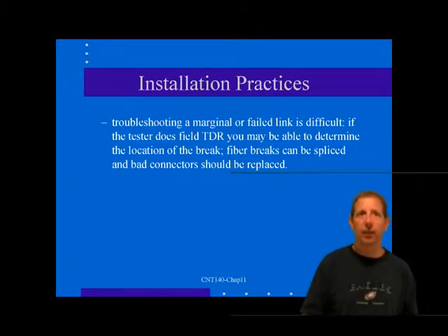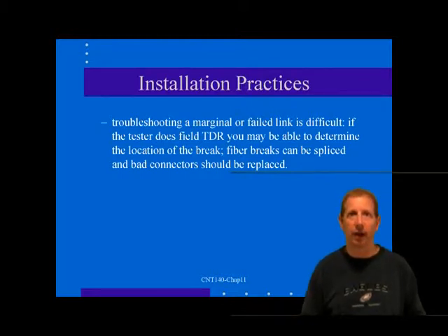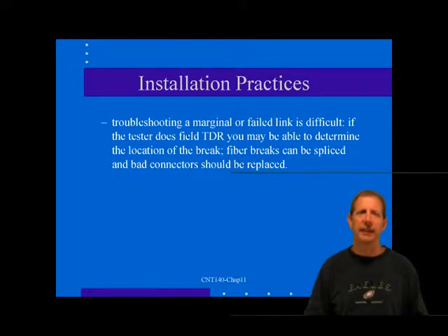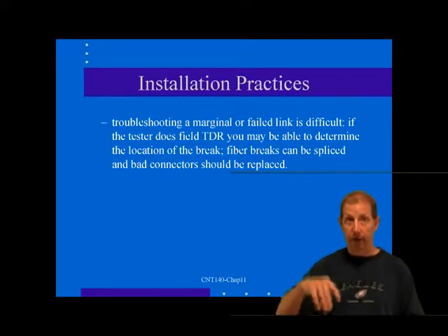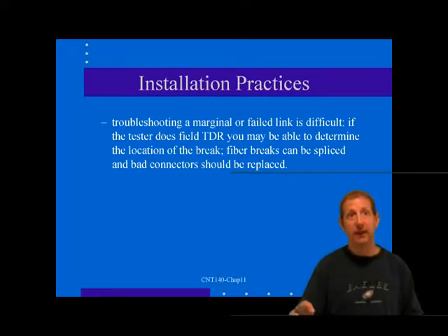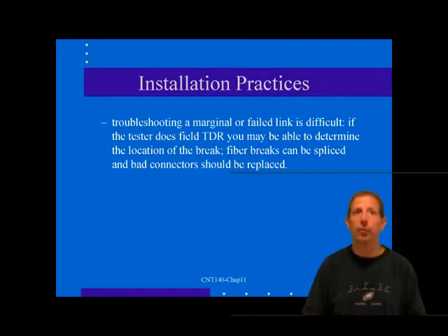A really sophisticated test would be to measure the link's bandwidth length product, and it would catch cables that have insufficient bandwidth for gigaspeed operation at their extended distances. Most fiber optic testers use the overfilled launch testing method, where the entire fiber core is flooded with light, usually from an LED source. This method is effective in dealing with 50 and 62.5 core diameters. In testers that use a VCSEL diode source, a mode dispersion technique is used to avoid the mode blockage that can occur in some multimode fibers.